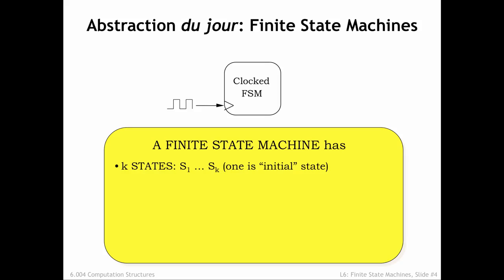One of the interesting challenges in designing an FSM is to determine the required number of states, since there's often a trade-off between the number of state bits and the complexity of the internal combinational logic required to compute the next state and outputs. There are some number of inputs used to convey all the external information necessary for the FSM to do its job. Again, there are interesting design trade-offs.